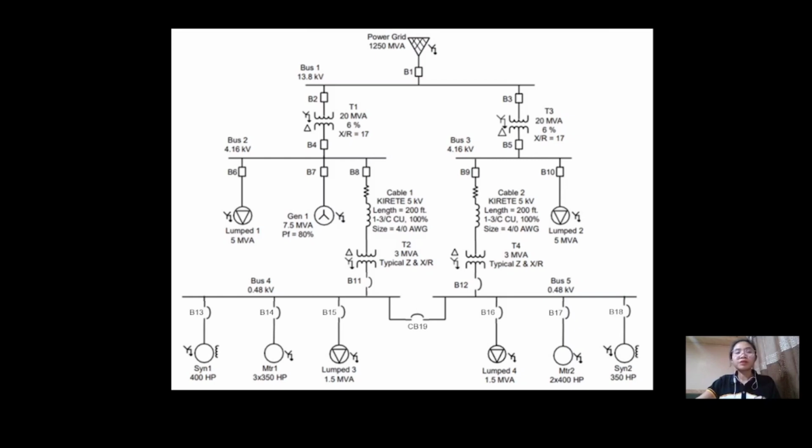To sum it all up, the main problem is how power is distributed under normal operating condition and under contingency condition. For example, in a scenario where transformer T3 is down, all the loads will be taken care of by transformer T1. What will happen to transformer T1? Is its capacity enough? What will happen to the voltage of the bus bars? Those are some of the questions that only fault analysis and simulation like ETAP can address.